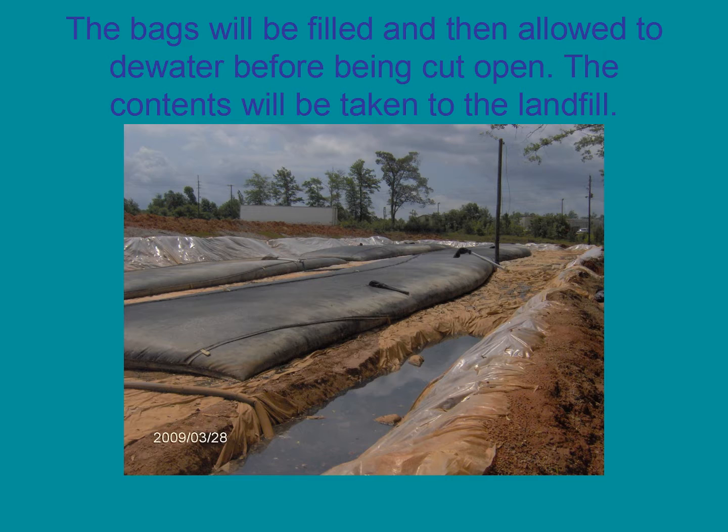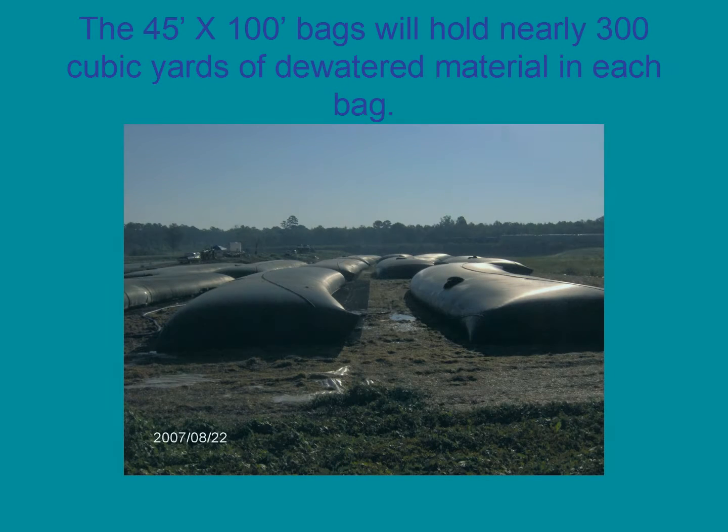The bags are repeatedly pumped up and allowed to dewater until they are full. The bags are allowed to dry, and then the solids are loaded out and taken to a landfill for disposal. The 45 by 100 foot dewatering bag will hold nearly 300 cubic yards of dewatered solids.